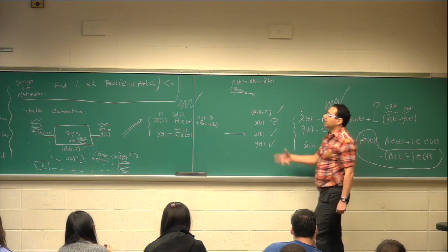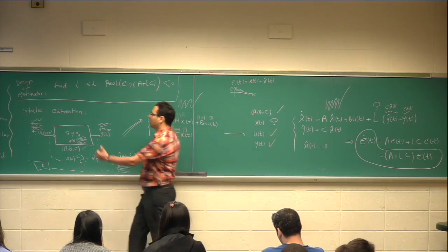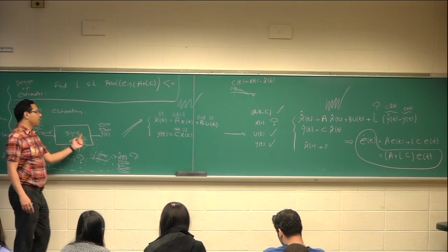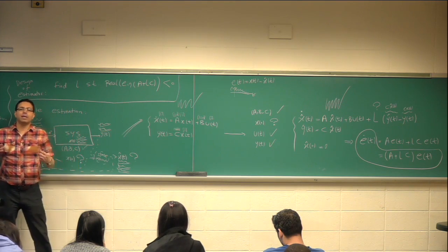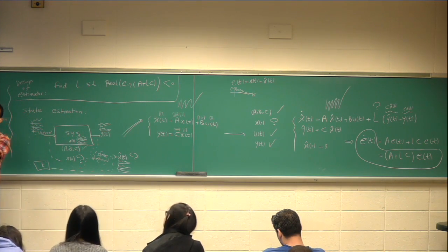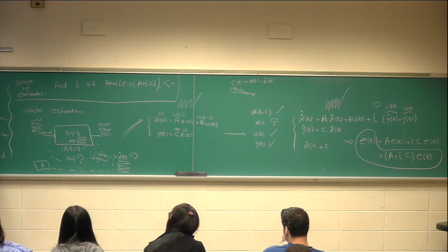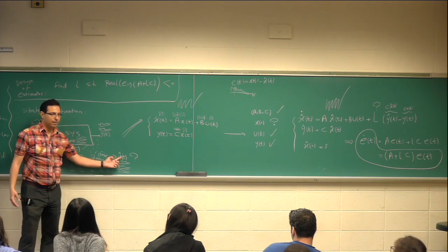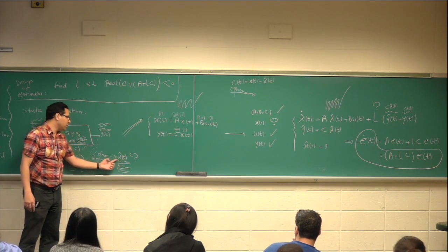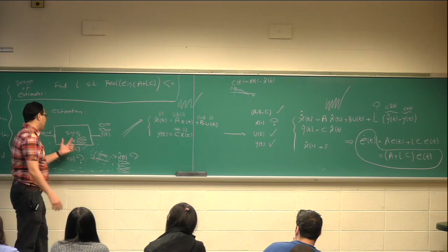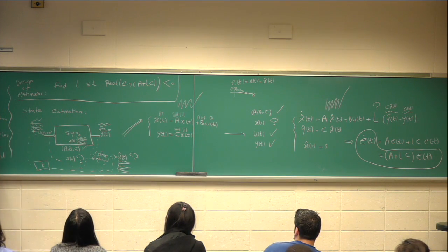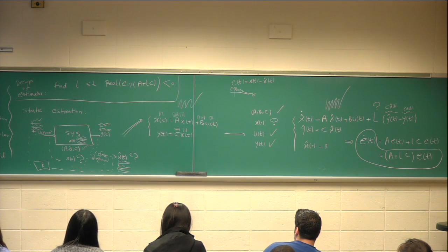So if you have a system like a power grid, you have a generator here, you apply mechanical power, you get electrical power here. There are many things that you cannot measure. There is a flux between, for example, the rotor and the stator. How can you measure it? You can do it indirectly through an estimator. Once we have a true estimation of all those parameters which are hard to measure, then we can design a feedback control. So this is about estimation that I didn't get a chance to talk about.